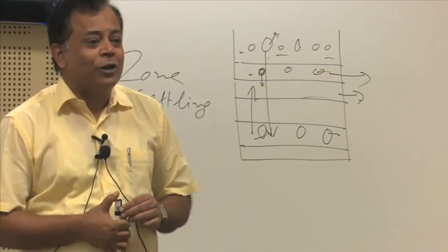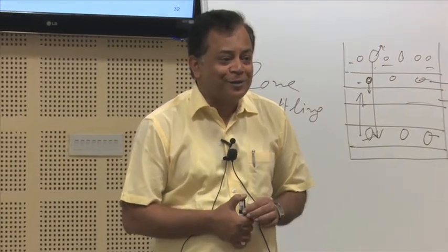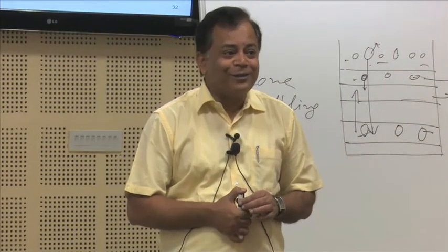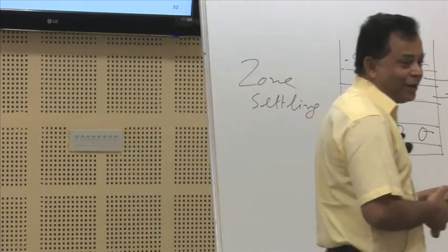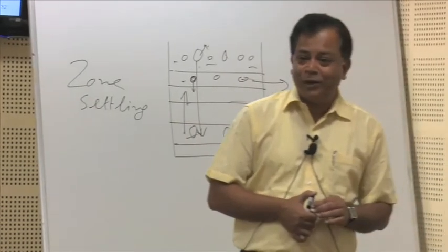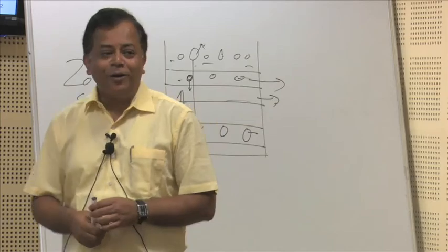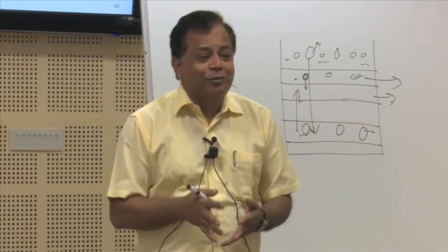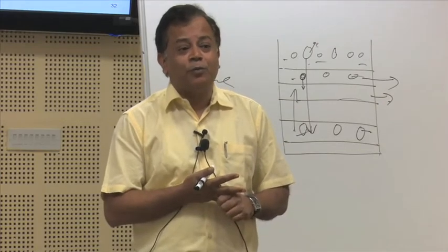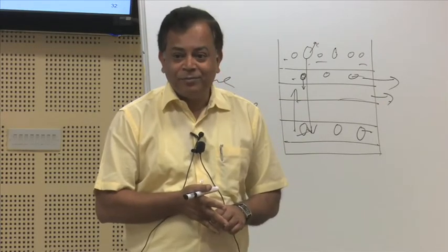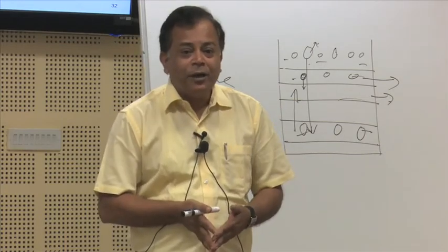So, that is called the counter flow factor. Because my big brothers are trying to go faster, your little brothers will have difficulties, they have to slow down further. So, where is that factor coming out? I need another correction factor for my hindered settling velocity when I have polydisperse and polydense suspensions. Are you getting there? When I have a density variation, when I have a size variation, I must introduce that.